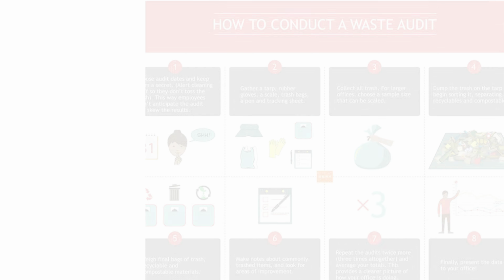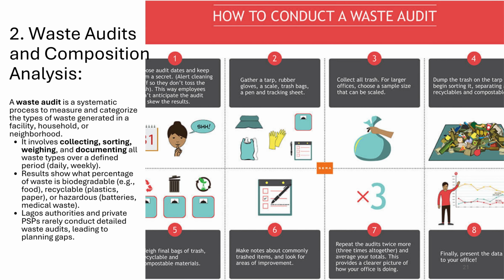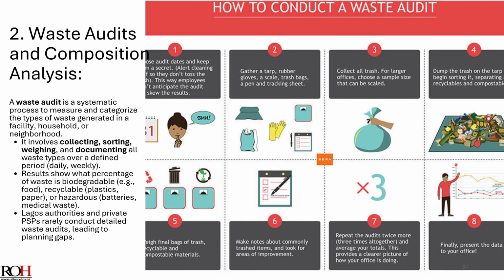2. Waste audits and composition analysis. A waste audit is a systematic process to measure and categorize the types of waste generated in a facility, household, or neighborhood. It involves collecting, sorting, weighing, and documenting all waste types over a defined period, daily or weekly.